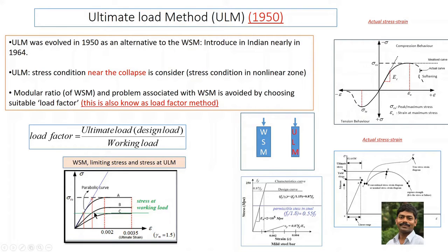Why am I saying this? Because I already used this graph to define the permissible stress for the limit state method. For the limit state method, the value is 0.45 fck, but for the working stress method, that value is 0.33 fck.